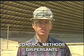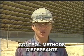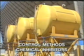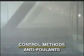There are several ways to control fouling in a heat exchanger. One way is to add dispersants. These will prevent insoluble materials like dirt from forming solid deposits. Another control method is to add chemical inhibitors that will keep chemical reactions from taking place. Or anti-foulants can be added to the process streams. These chemicals prevent biological growth.